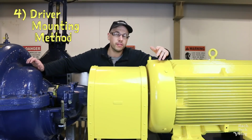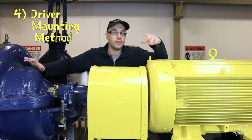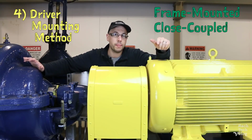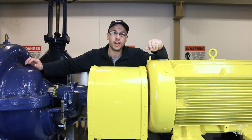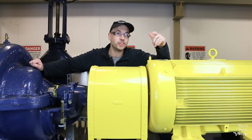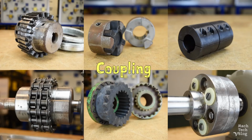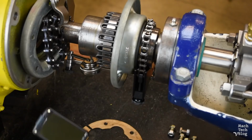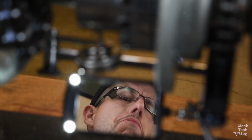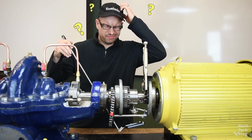There are two options for transmitting rotational force from the driver to the pump. Either frame-mounted or close-coupled. If the pump and driver are two separate units, as they are here, then the pump and driver shafts will need to be connected by some type of a coupling. Now, couplings come in all shapes, sizes, and styles, but one characteristic common to all of them is that they require proper alignment of the shafts, and that can be a very finicky process indeed.